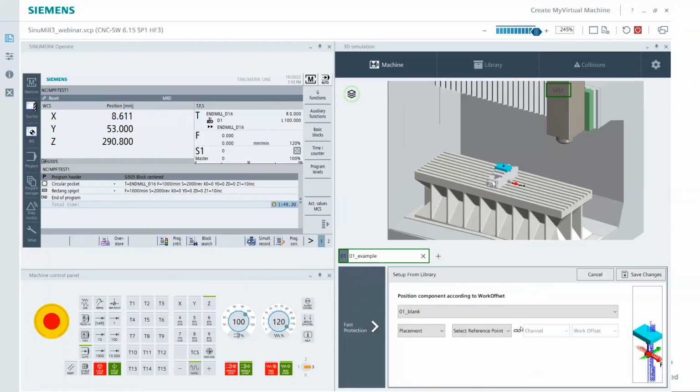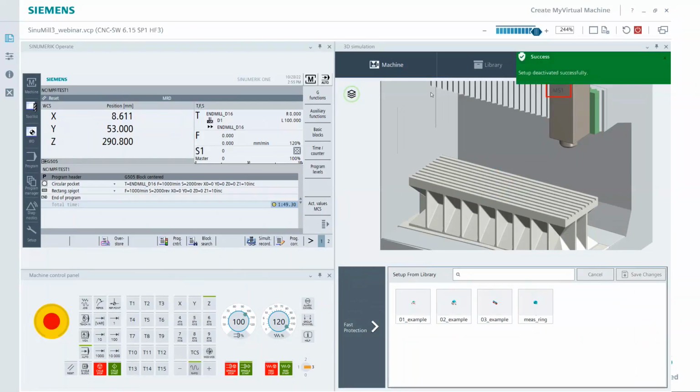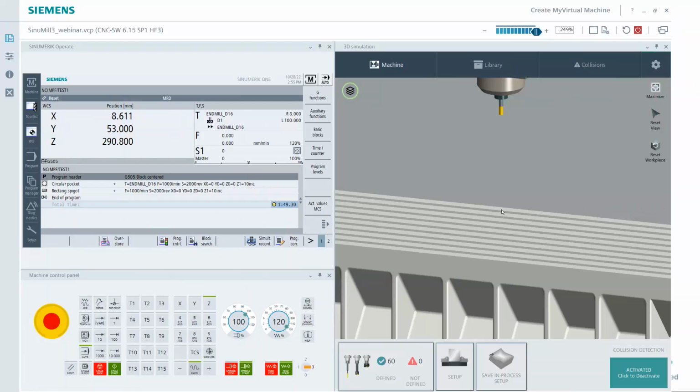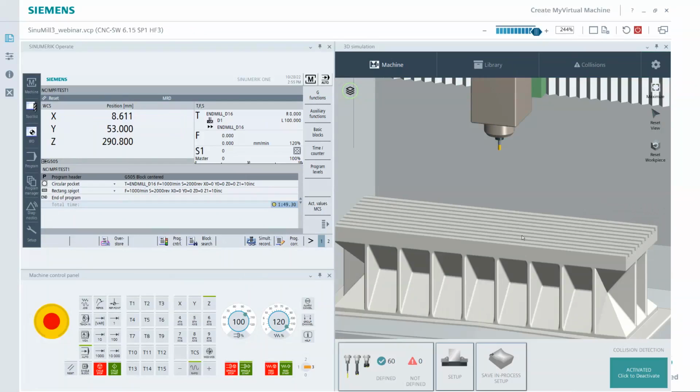We're going to get rid of our little example setup, and we're going to import a machine, and some work holding. It is a good habit to get into, when you're going to do anything on your setups, to remove the one that's on the table, because at some point you're going to be putting a new one on, but also you can't edit the one that's already mounted to the machine. So if you're always in the habit of removing the setup before you make any changes, it keeps you from getting an alarm telling you, hey, you're trying to manipulate the setup that's already loaded.